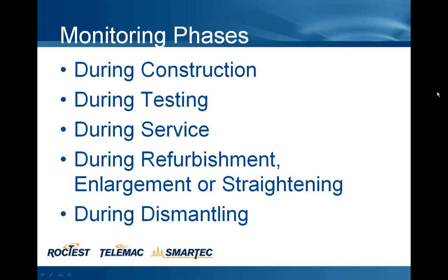Monitoring can be useful during several phases of the lifetime of a structure, basically all of them: during the construction, in particular any critical stages of construction, during the testing phase, of course during the use of the structure, the service phase, during any action of refurbishing, maintaining, enlarging or strengthening the structure, or even during dismantling. We have been sometimes asked to monitor structures that were intentionally damaged to learn something about them in the end of their life.